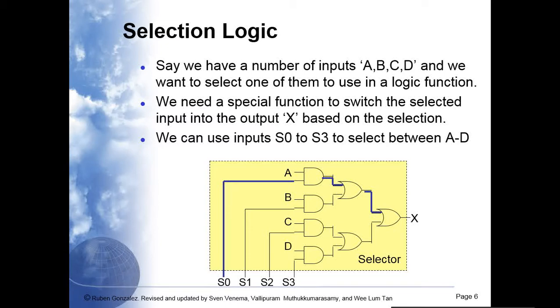And OR gates collect things. They group things together. They let things through, actually. Yeah? As long as you've got a 1 anywhere, there's a 1 on the output. So the first row, the A, B, C, D, those AND gates, they stop things from going through. One of them will let something through. What about the OR gates? Well, once something comes through, you want to know about it, so you let that one through. Okay, that's how that works.